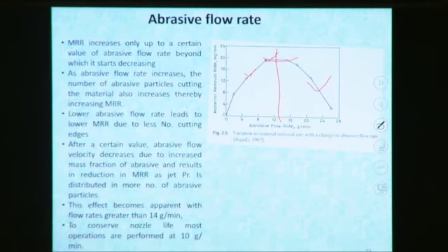So as more abrasive particles take part in the machining, what will happen? Individual abrasive velocity will reduce. So MRR increases only up to a certain value of abrasive flow rate, beyond which it starts decreasing.